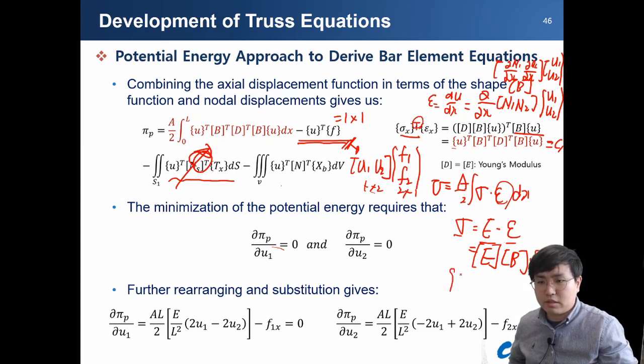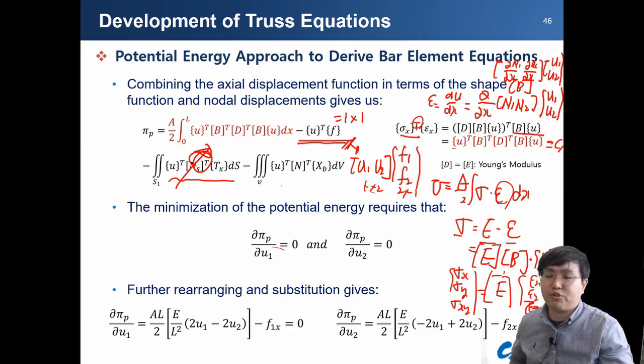However, let's consider the two-dimensional case. We have 3 components here, similarly with a Young's modulus matrix, and this strain, this is a shear strain, so they have an expanded vector form equation. To match those relationships, this is energy, so it becomes a scalar value. With 3 by 1 and 3 by 1, without the transpose operator that cannot become a scalar value, so it becomes a 1 by 3 matrix, and we need the transpose operator here.